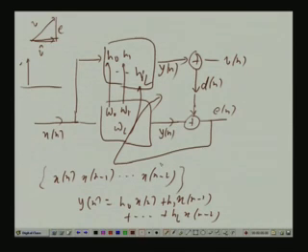This is called system identification. There are many other applications: adaptive noise cancellation, interference suppression and all that, adaptive beamforming, which is very much used in smart antenna applications. Suppose there are several persons using the same frequency band but sending signals from different directions, and I want to receive only one and I do not want to hear others. It is very useful in today's mobile communication.